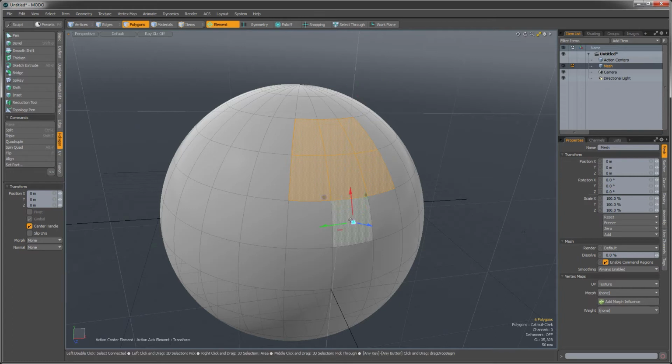If you click on that, it automatically aligns the tool to the normal of the element that you clicked on, and then positions it at the location where the mouse click intersects with the surface. So now we can move elements based on that position. Undo, we can click there and move them like that. So it's a very easy way to position your handles.